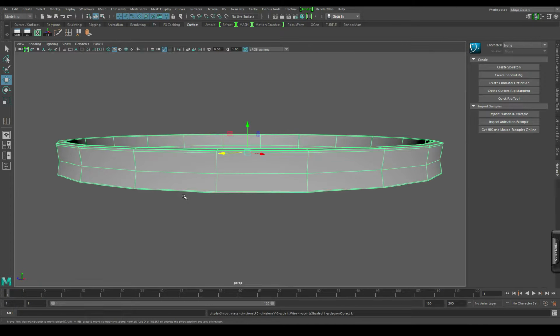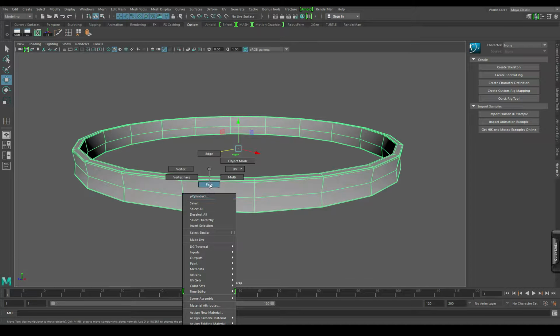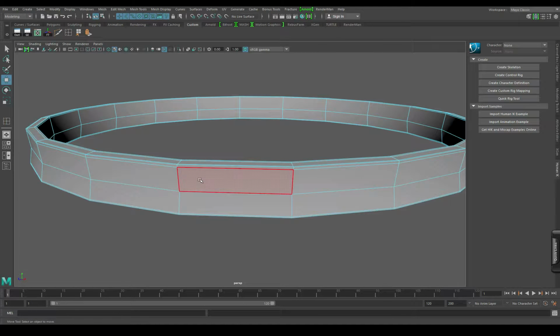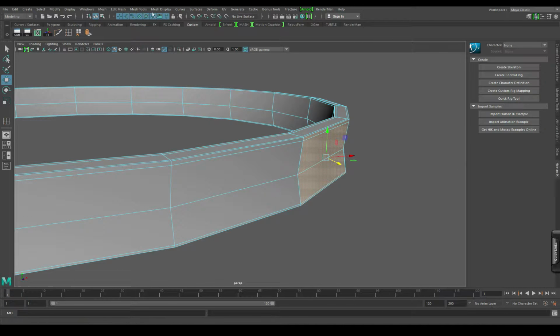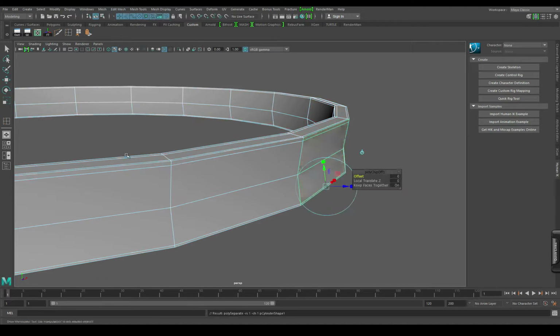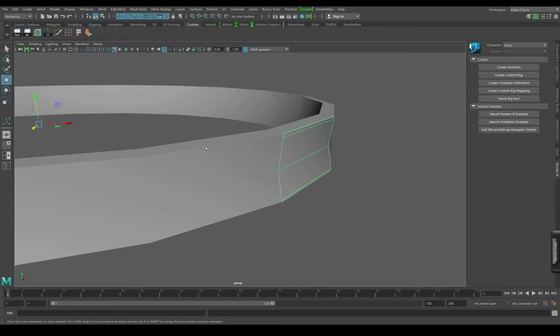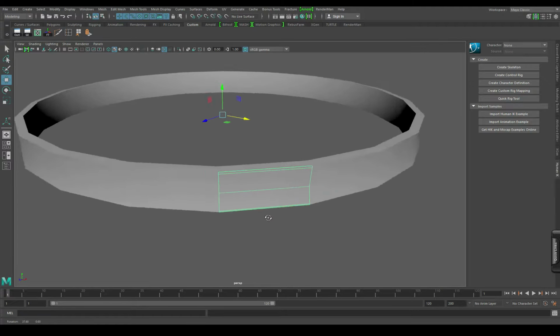So there, I've got a belt. What do I want to do with it? Well, I want to put a couple of bags on it. Let's call it like a utility belt for an army dude, okay? An army dude. So I'll select those, the sides there. I'll go to mesh, edit mesh, and at the bottom there, duplicate. So I duplicate those faces, you can see. Then I'll go back to object mode, move, hold down control and deselect the main one. And now check at this. I've got this cool little thing that matches exactly the original.